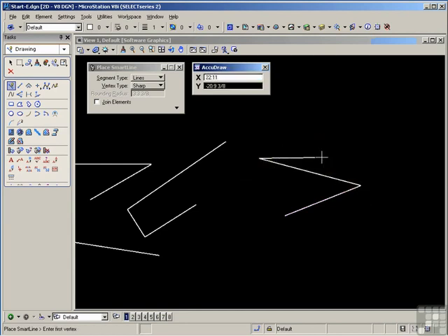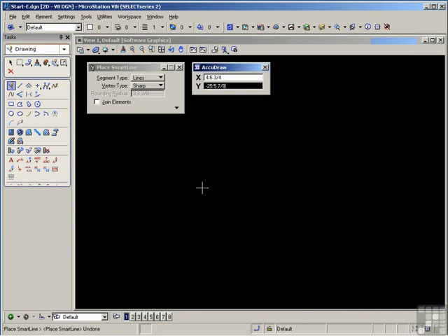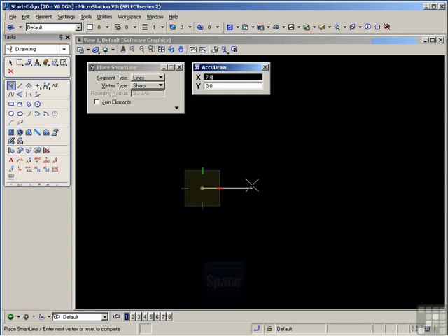Now this is the simplest and most basic mode of operation for AccuDraw. I'm going to undo those line placements. Now, AccuDraw actually has two compass modes. One for rectangular coordinates, which is what you've looked at right now, and that is the square compass. But it also has a polar compass, and you can see that by pressing the spacebar. If I keep pressing the spacebar, it switches between the polar compass and the rectangular compass. Switch to the polar compass.